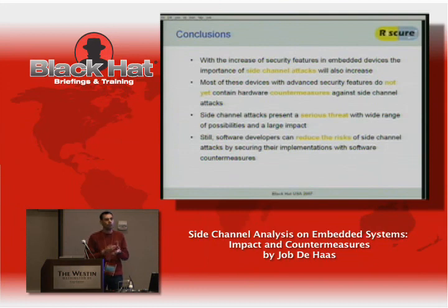If you store a secret in there, then you can do a successful attack. Do note that an important step is that you can control the crypto operation as accurately as possible. Running your own code on the system is not a precondition, but it's very nice to have. Or you have to have a way to drive the crypto with your own input or get the output in a consistent way somehow.